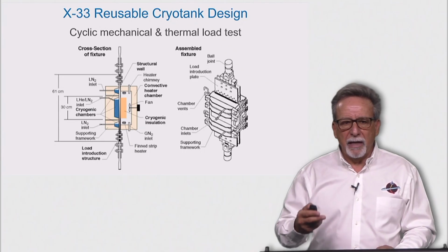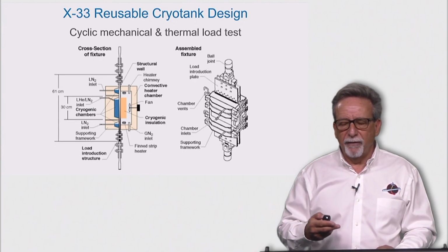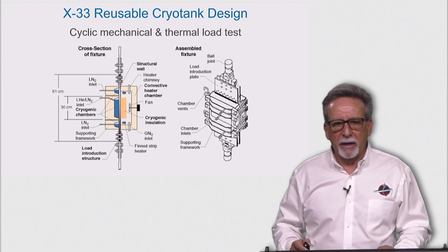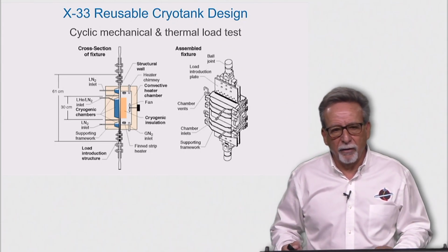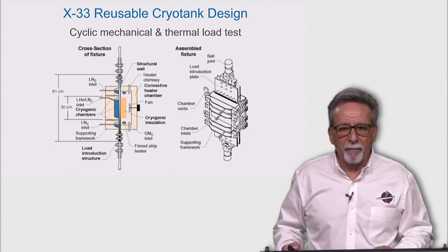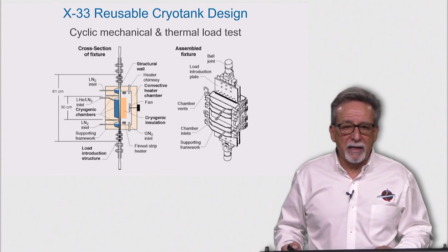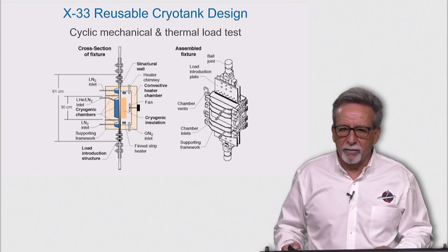Once the contractor accurately incorporated the out-of-plane deformation the pressure vessel would see during real loading, it was soon realized that the brittle foam's low strain to failure caused unacceptable damage, and no increase in the density of the foam could sustain this ultimate failure. By recreating the critical failure mechanisms and designing intelligent tests early, you can evaluate many concepts quickly and inexpensively.